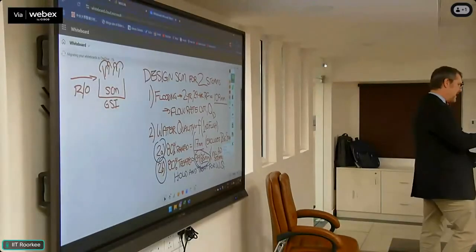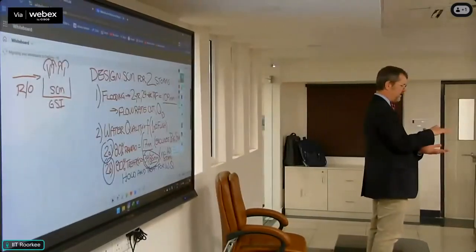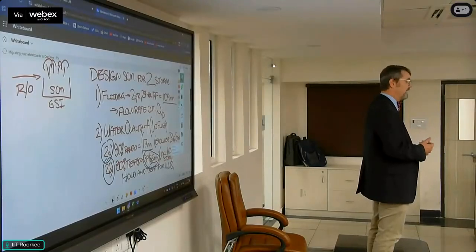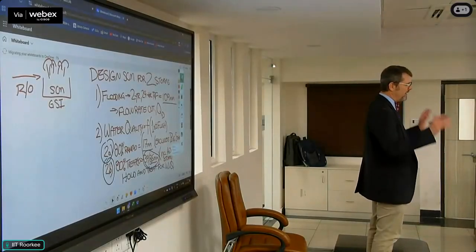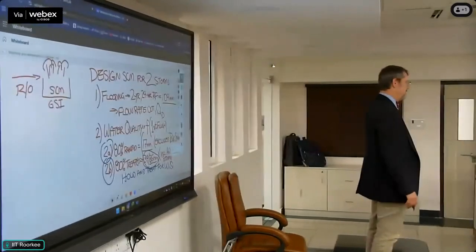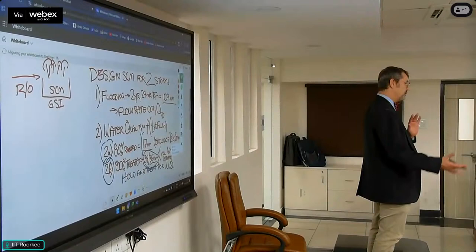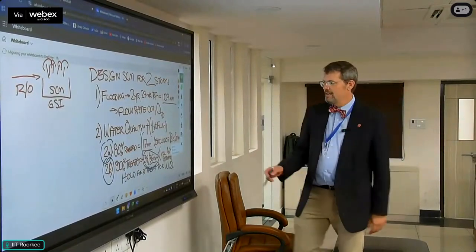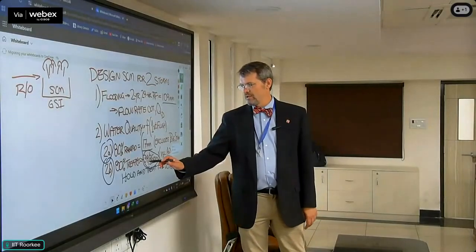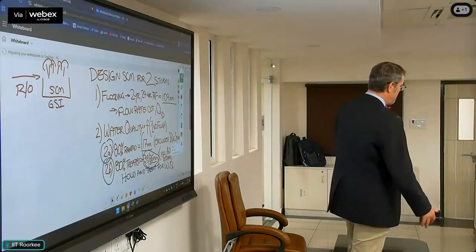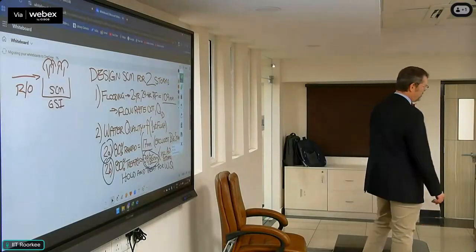And if you have a fixed depth, which you do, which we'll talk about in the coming days, that literally makes your practice twice as big. And so for some people, I'm like, you know what? I can't afford that. But if you want to be true and get 90% of the pollutant load, then the better number to use is 34 or 35 millimeters, because that's going to subject roughly 90% of the pollutant load to treatment.